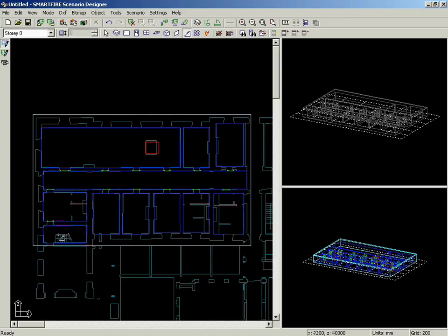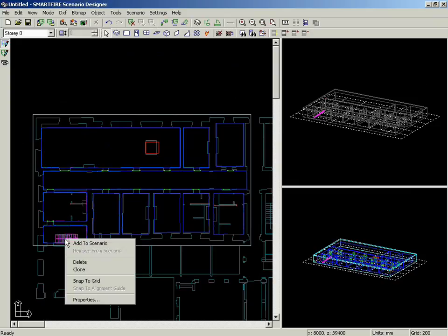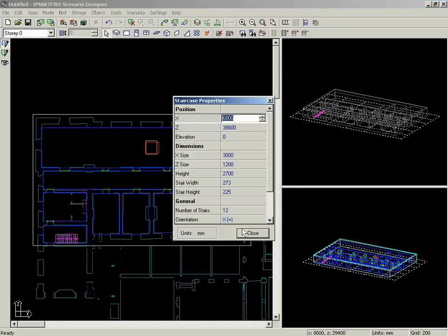I'm going to choose to make this building multi-story, so I'm going to link the stories together with stairs. But because I want the simulation to run quite quickly, I'm going to choose to have only a few stairs representative of what will be in the real building. This cuts down on the mesh budget requirements.